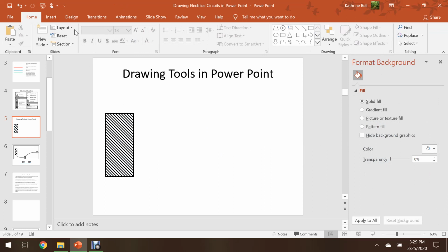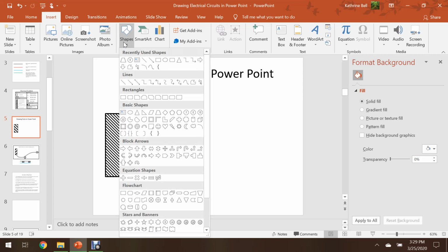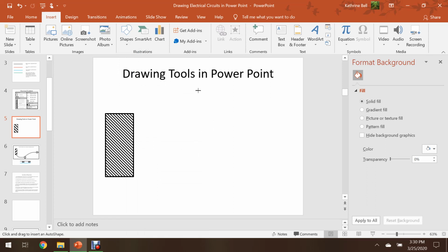Other commonly used shapes that we'll use will be those for device boxes. The first device box that we're going to do is an octagonal box. I've used the octagon shape tool many times. If you do not see it in the top tier, simply come down to Basic Shapes, select the octagon, click on it and release.